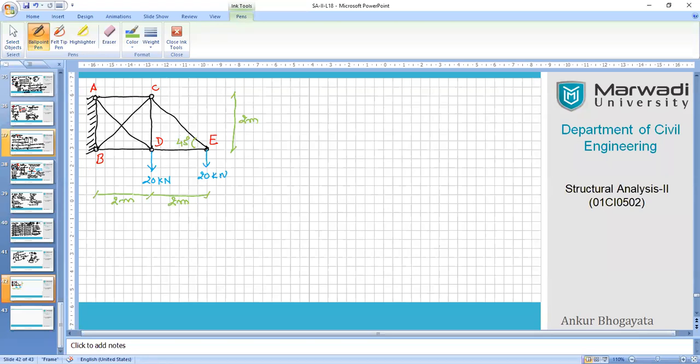All right, then this is enough for us, and we'll write down the values of E and I in this case also. Let me give you E, that is 2 × 10 to the power 5 Newton per mm square, of course, it is a steel member. And the moment of inertia of the members, sorry, the area, not the inertia, the area where we require cross sectional area. That is 1000 mm square. Yes, it is 1000 mm square.